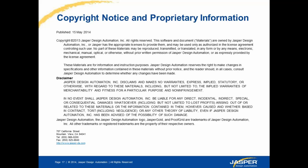If you're going to use branch coverage or expression coverage, you can add them all, and you can run all these metrics in the coverage app to get you a much better idea of the quality of verification done. So if you're just going to use line coverage, then that is what you're going to get. If you add branch coverage, toggle coverage, or expression coverage, then that will give you a much better metric to qualify the verification you have done so far.